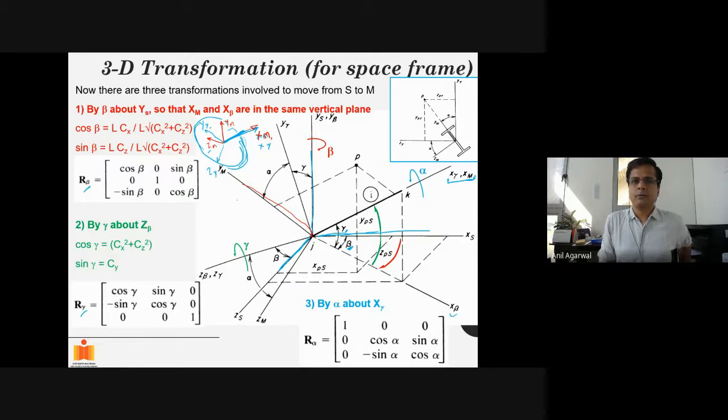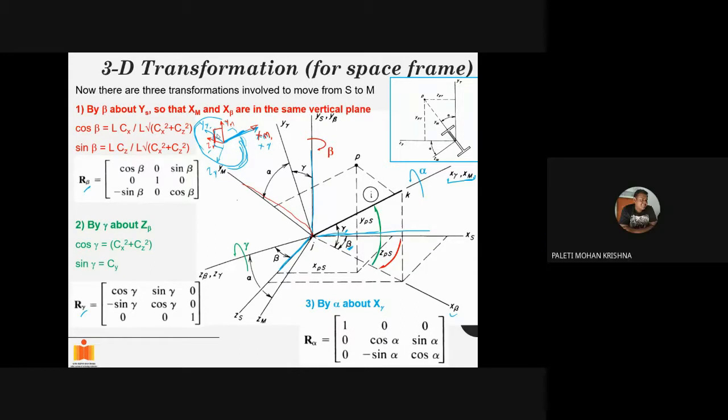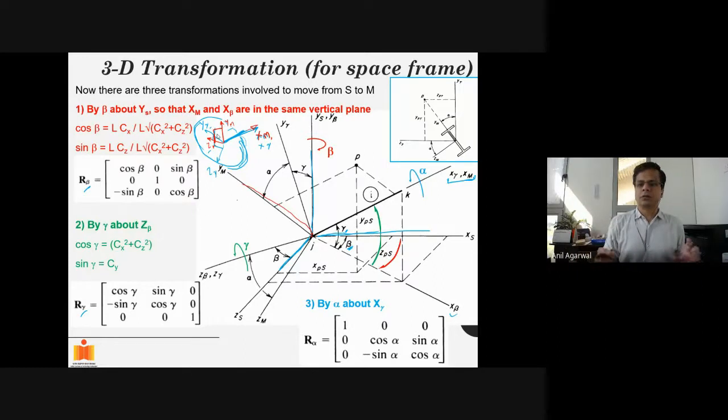And this is perpendicular to this one, and this is perpendicular to this one, right? So zm is perpendicular to ym, and z gamma is perpendicular to y gamma. So what do we know from here? Which rotation is required to align all three of them? About the x-axis, right? And that rotation we call alpha rotation. So I just need to rotate about x gamma, okay?